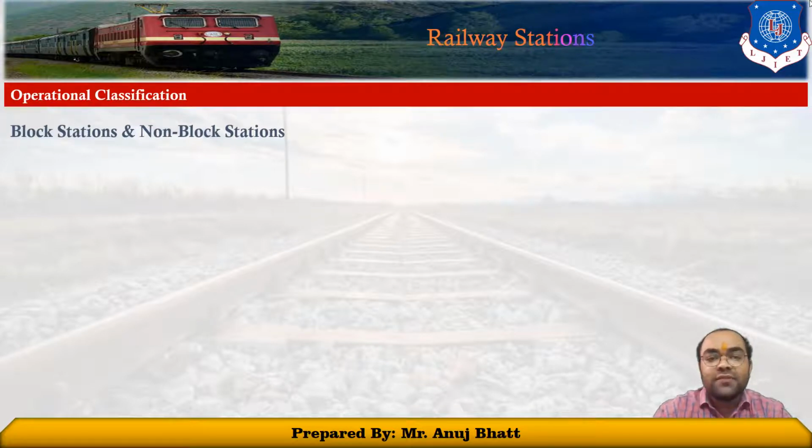Well, in the block stations, we have a few categories: A, B, and C class stations. This block station is a station at which the driver has to obtain an authority to proceed in order to enter the next block station. In a railway system inclusive of block stations, the entire railway line is divided into convenient block sections, such as of 5 to 10 kilometers, and a block station is provided at the end of each block. The system ensures that a suitable space interval is provided between the running trains so that there are no collisions and accidents.